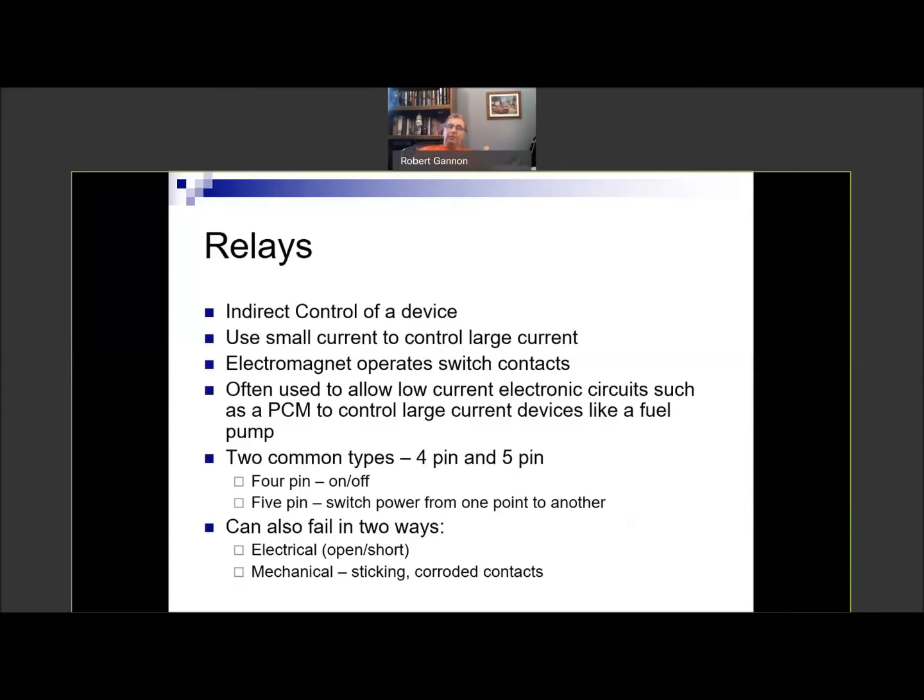That's not necessarily the case. Just because a relay makes noise doesn't mean it has any current flowing through it. It was admittedly a strange one. You don't see that too often. But, just like a solenoid, it could fail electrically, so the relay coil has an open or a short. Or it could fail mechanically, so it gets stuck. I've heard of relays sticking on, and whatever is being controlled by it just won't shut off, even when you turn off the controls to it.